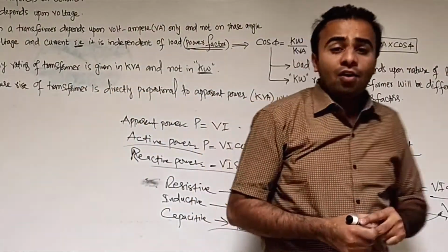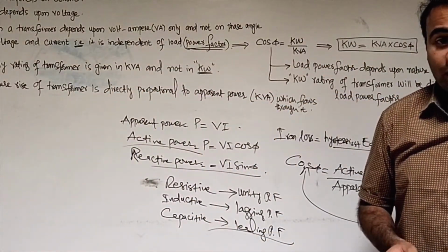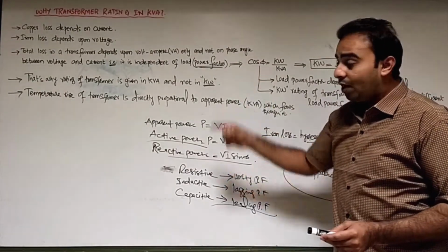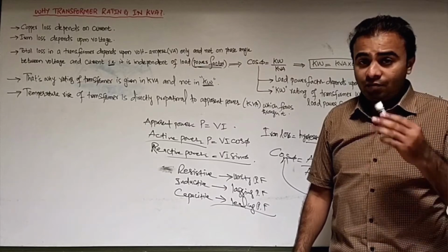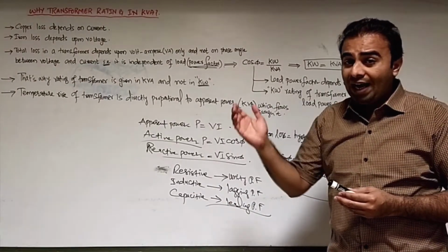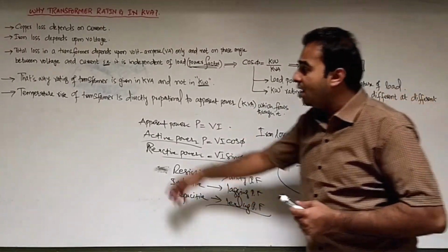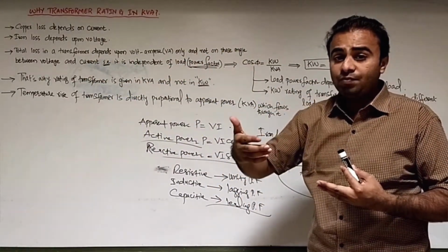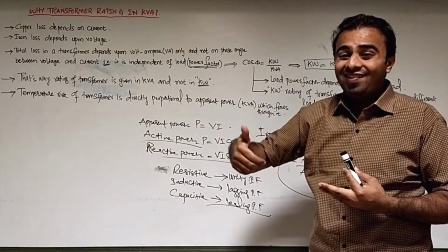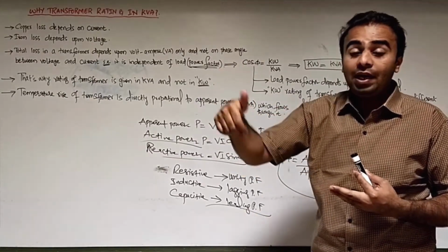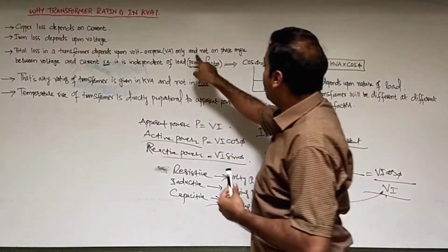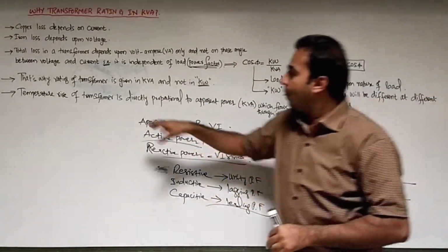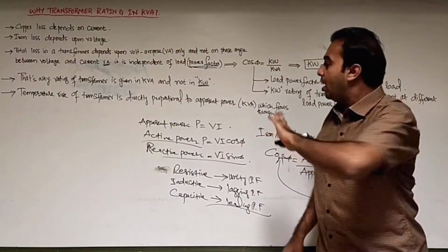So while designing electrical machines, we do not know what kind of load will be connected with the transformer. So why are transformers rated in kVA? Because the k shows the value of kilo, since our power transformers, our large transformers, are rated in terms like kVA and MVA. So here we are not only considering the phase angle. It is independent of the load power factor.